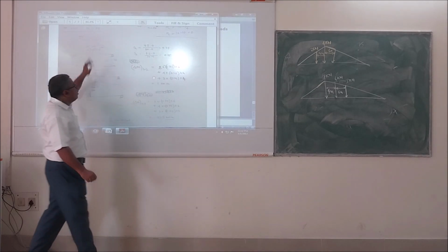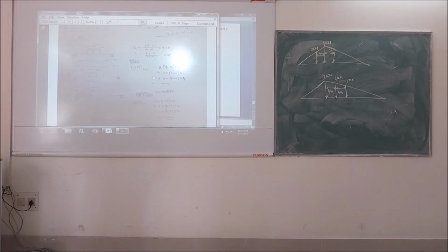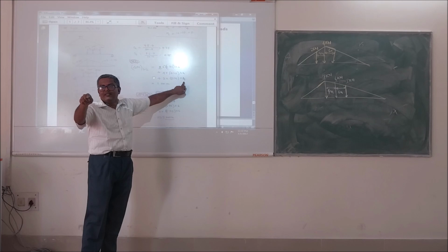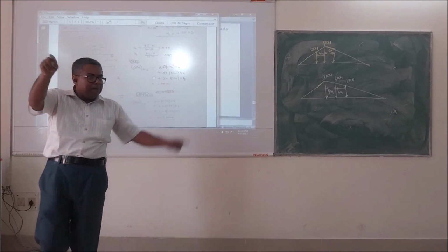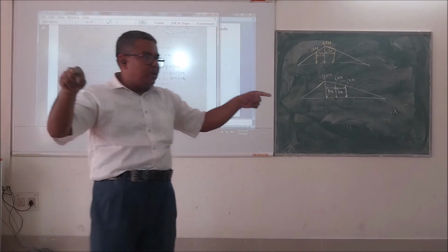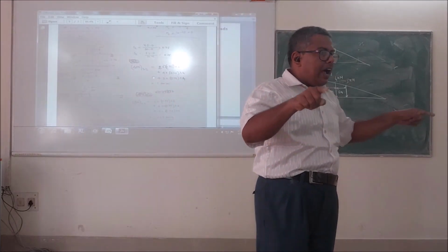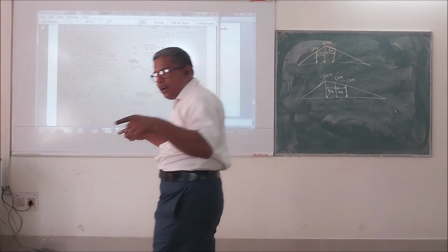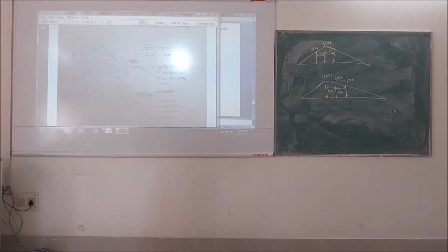Next, 3 kilonewton load. What will happen to 3 kilonewton load? See, most of the time you make a mistake, you multiply this with 6. This is the mistake being done. Because when the 1.5 meter equidistant loads we were studying, at that time there was no confusion.